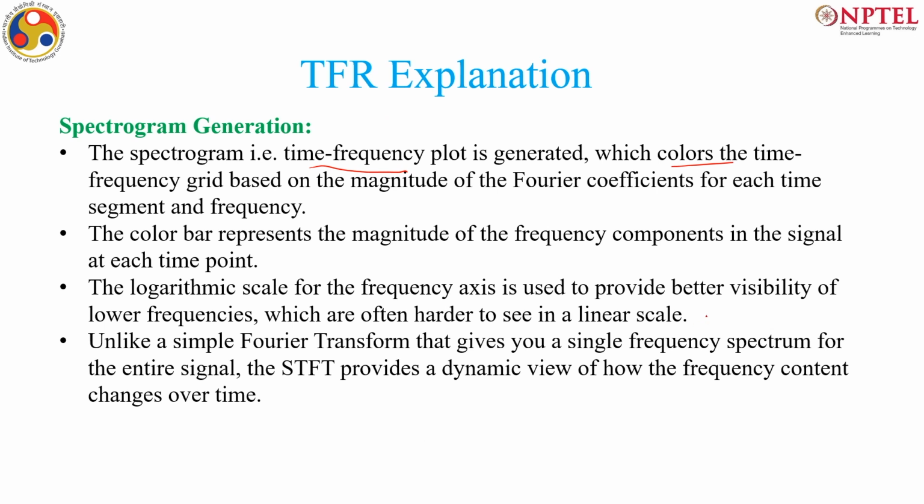And we have used a logarithmic scale, because on a linear scale it would be harder to see, because the frequency is increasing very fast, like we have 10 square and 10 cube. In a logarithmic scale 10, 10 square, 10 cube will be equally spaced. So, we see that this STFT provides a dynamic view of how the frequency contents are changing over time, unlike our simple Fourier transform that gives a single spectra of what frequencies are present.